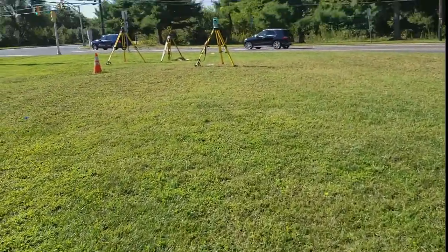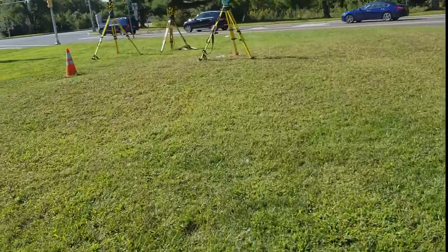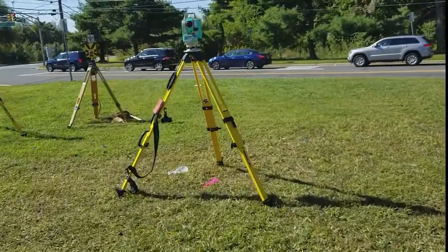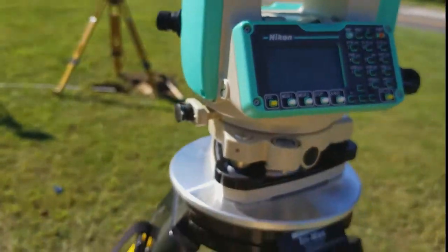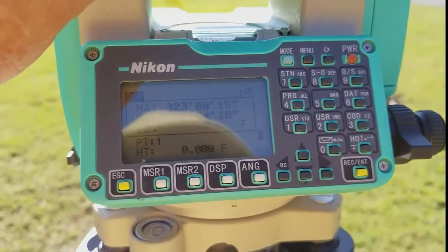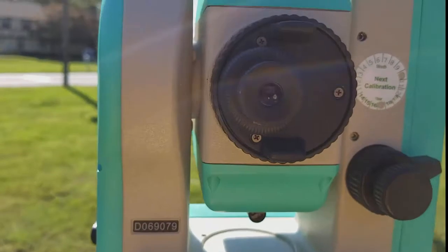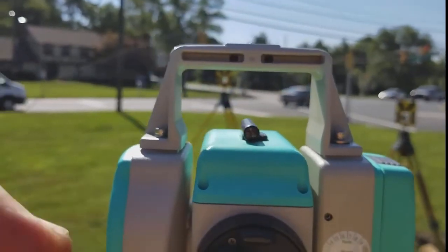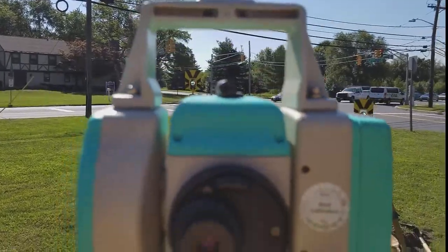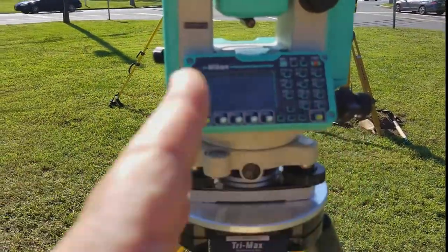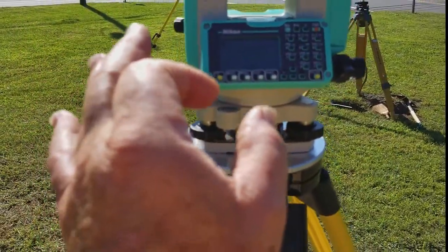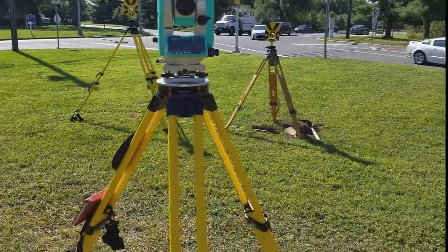What I'm going to use is just this electronic instrument. And the advantage to this one, of course, is that it measures distances. Now, so this is a digital theodolite. It's a 1 arcsecond theodolite, but it measures distances. And I'm going to need to record distances on this test, because what you're going to find out is that the angular differences will get smaller and smaller and smaller the further and further and further away you are.